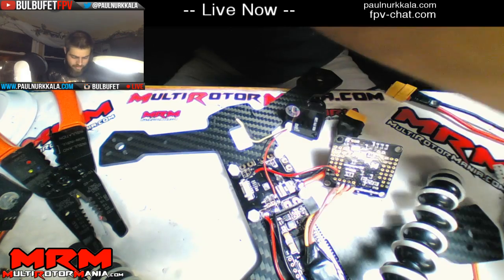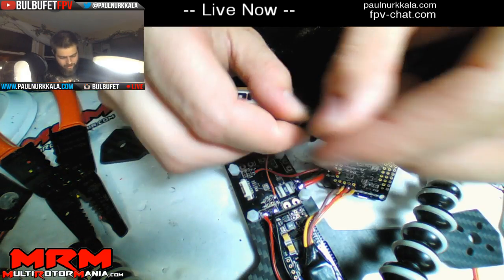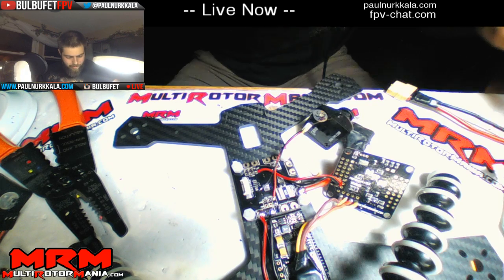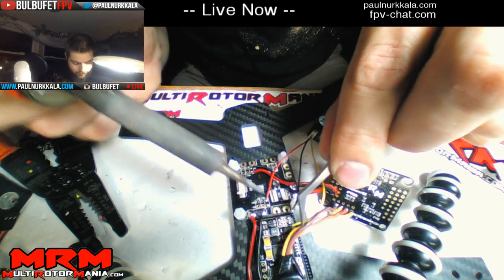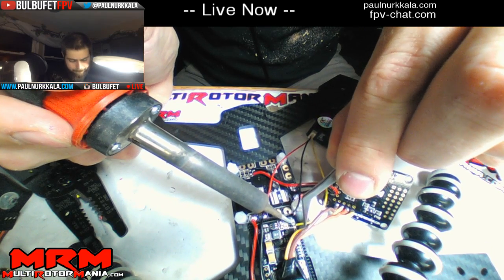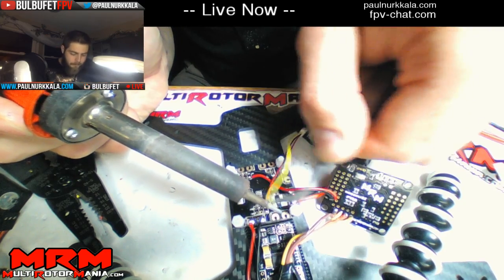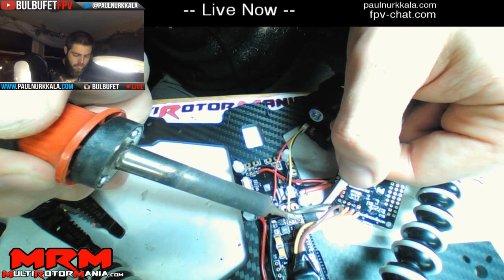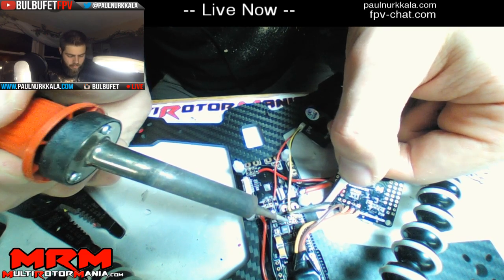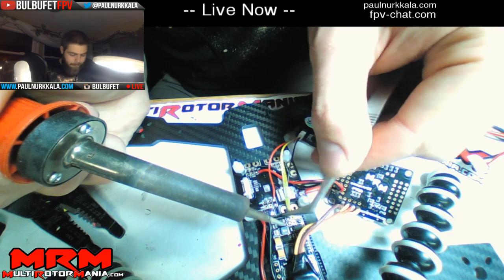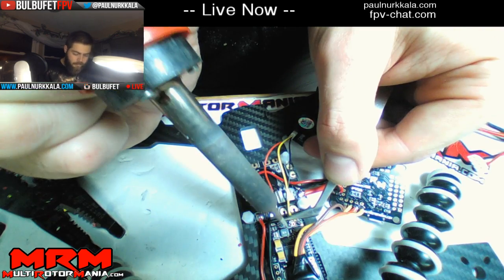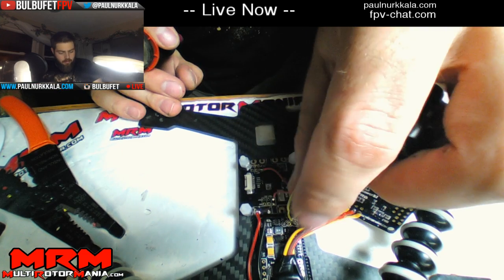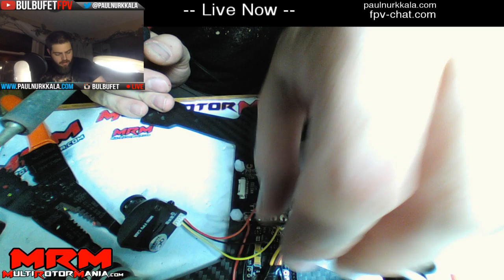Now, this video in is going to go to that back point, and this ground is going to go to either one of those because they're the same. But I'm going to mirror them. So if we go here, yeah. There's the video and the ground for this whole thing. Okay, so now we have the camera wired up, ready to go. I'm going to move these wires out of the way so we can get our VTX in here now.